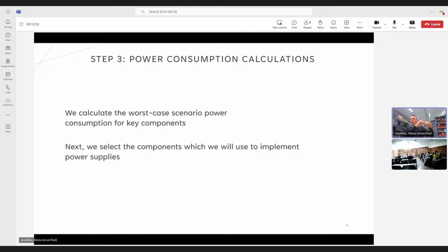So you just draw the input source, and then you make all the branches, and you make all the dependencies there. You draw that, and that power tree is actually, let's call it a power supply architecture, and it's a separate topic. You cannot tackle these kinds of problems anymore in the way it was done before, where you have one or two rails and that's it. Now it's complex, and you really need to pay specific attention to that.